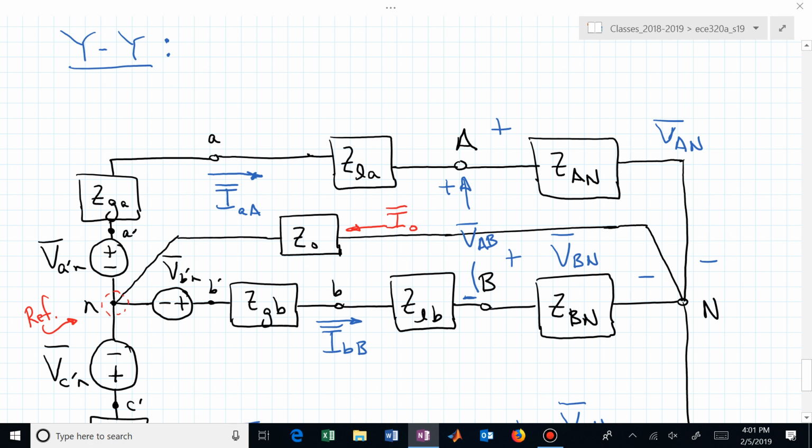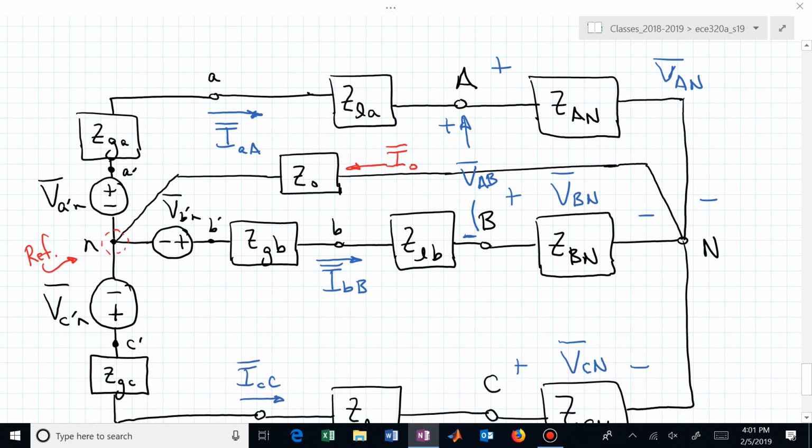And if that's the case, now we can actually just extract that very top mesh into a single-phase equivalent. Z sub 0 is immaterial. Since there's no voltage dropped across it, we can just replace it with a pure line.